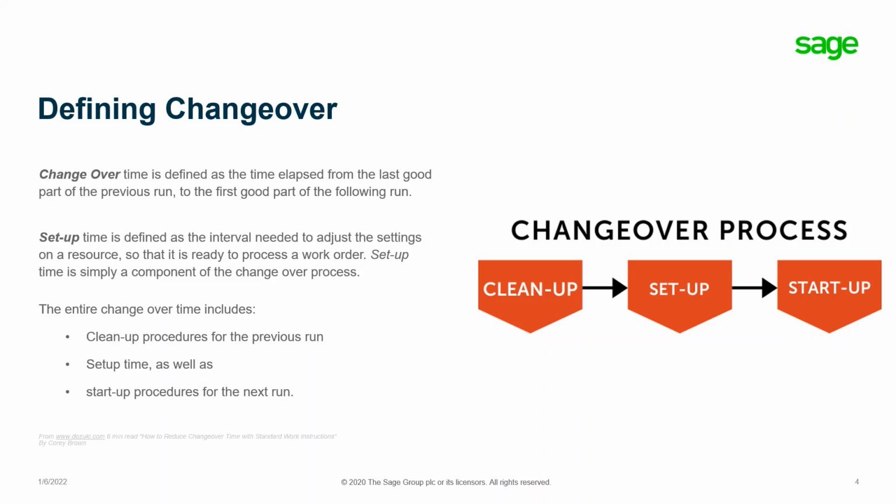Changeover time is defined as the time elapsed from the last good part of the previous run to the first good part of the following run. Often, changeover time and setup are used interchangeably, but setup time is simply a component of changeover time. In a perfect world, we would have absolutely no changeover.